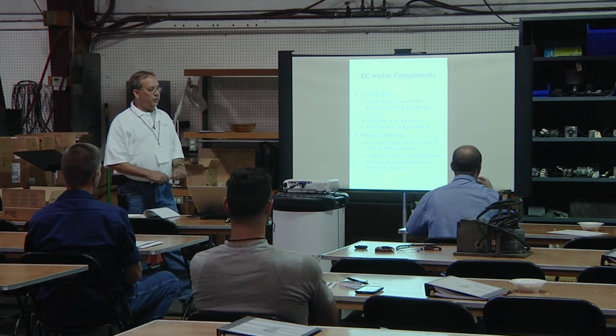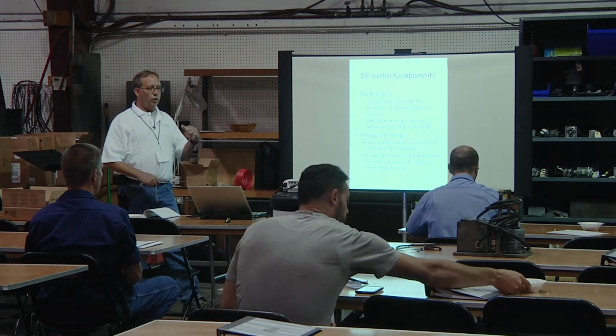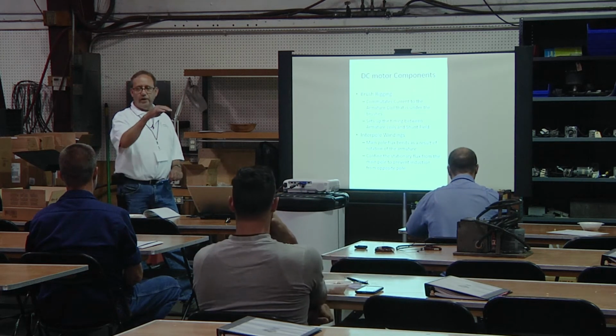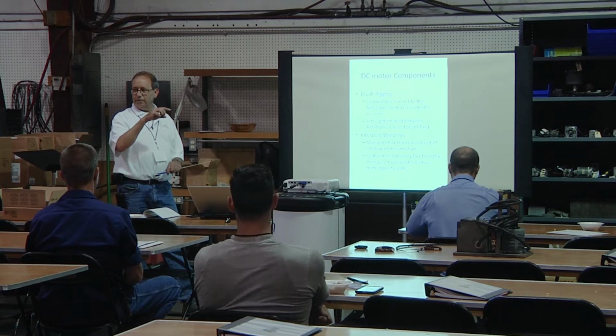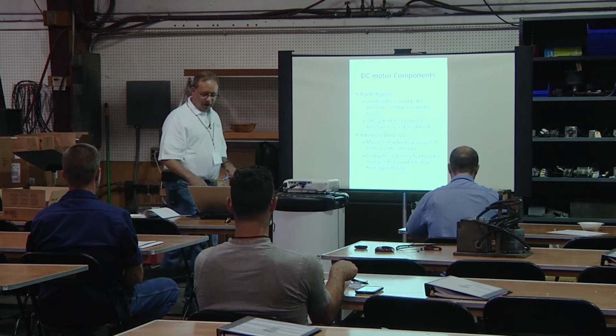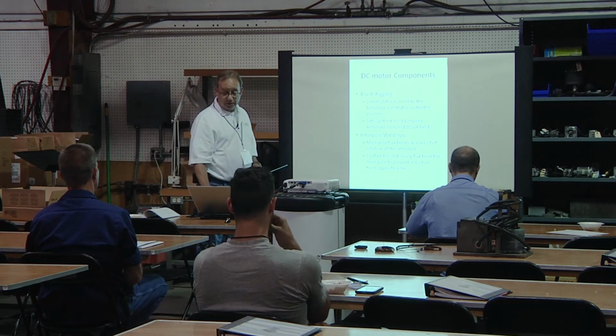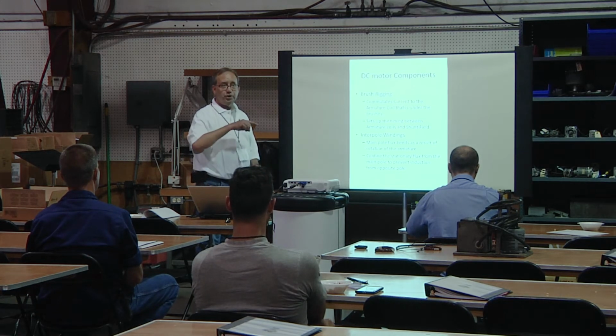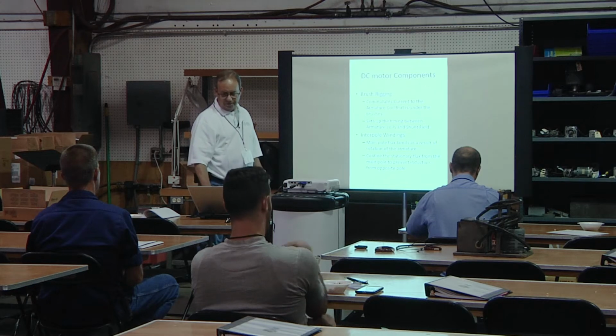So if you get grooved comms that are down to where the brushes are riding actually off that, you saw the undercut between the comm segments over there. If it's riding on that mica, those brushes aren't going to last. It's just going to cause you more problems. It's easier to get it out, turn the comm. We've got a machine to undercut those mica slots, get it all cleaned up for you.